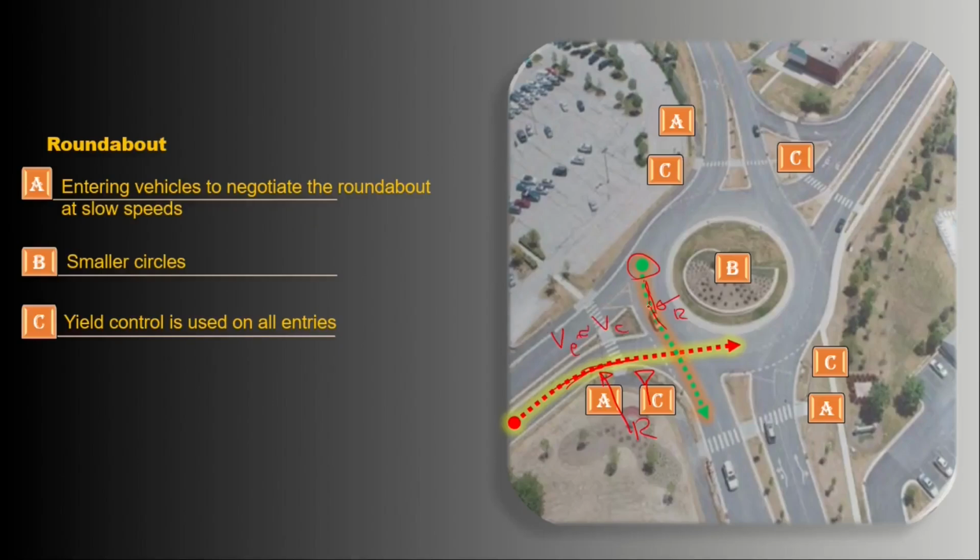same speed. Since the entering traffic has to cross the circulating traffic path to enter the circle, and they're operating at almost the same speed, it makes it difficult for entering traffic to keep the priority, and it also gives the circulating traffic enough courage to grab the priority.